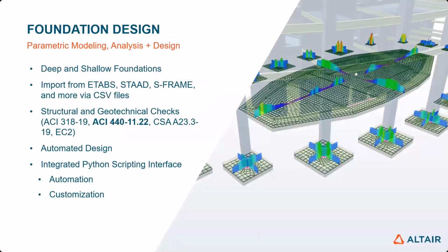We've also implemented GFRP rebar design into our foundation design software, S Foundation. This can be used for deep and shallow foundations, and allows you to design your foundations as either a standalone workflow, where you define your foundations directly within the software and apply your loads manually. You can also integrate the software that you use for your analysis, whether it's ETABS, STAAD, or SAP, or if you just have a CSV file with all the foundation support locations and reaction loads, that can be brought in as well. So it can be fairly agnostic in terms of where the data came from.